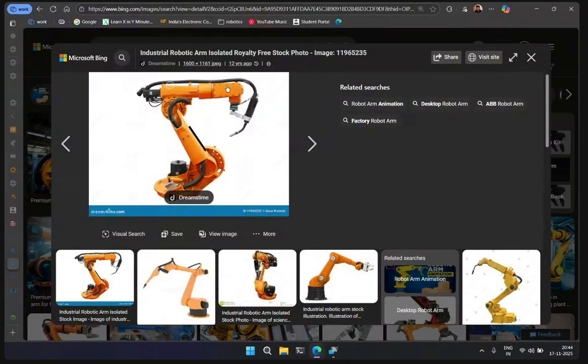Here, this one, this part. Inside this one part, you will have a lot of gears inside, which moves all these three. And how will you reach it? That's why they have multiple openings here. You have an opening here to reach this point to lubricate it, and this one also. Inside this, there's a planetary gear system.